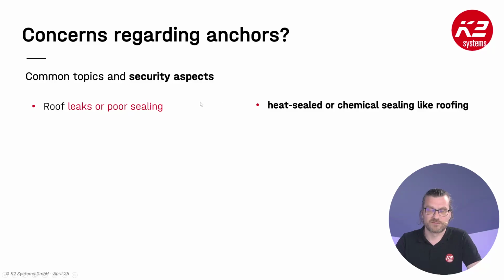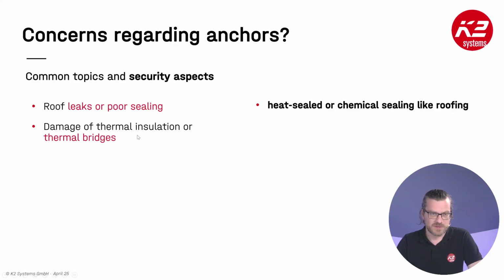You have to understand that if you install an anchor, you will weld it, and the installation at the end, on the top, will be the same as your foil, which is already installed on your roof, because the anchor will be completely welded. There will be no space for water to come underneath the anchor, so your roof will still be completely watertight. Next one.